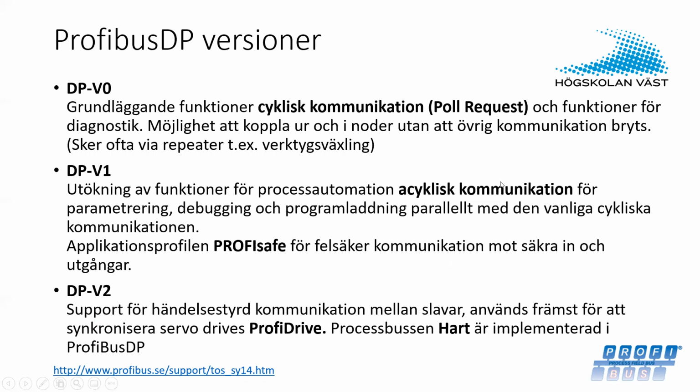For example, you need some acyclic communication, and that might mean that you need to program sensors, debug sensors. You need to load new programs or firmwares in sensors. You have this kind of managing or administration traffic that's not part of the regular operation. So they have support for this kind of acyclic communication. That might be larger chunks of traffic, but not this cyclic, regular, real-time traffic.